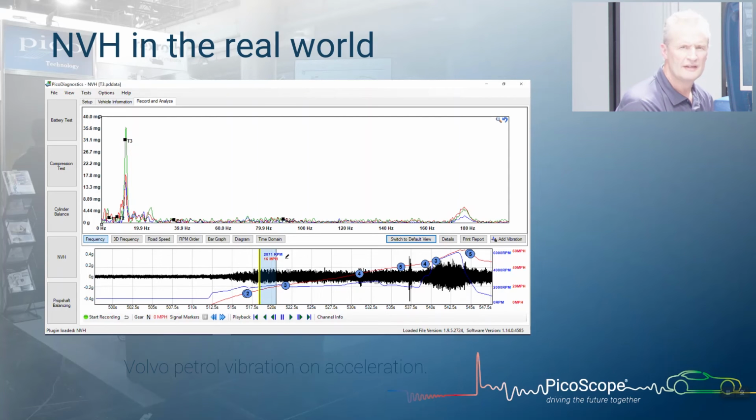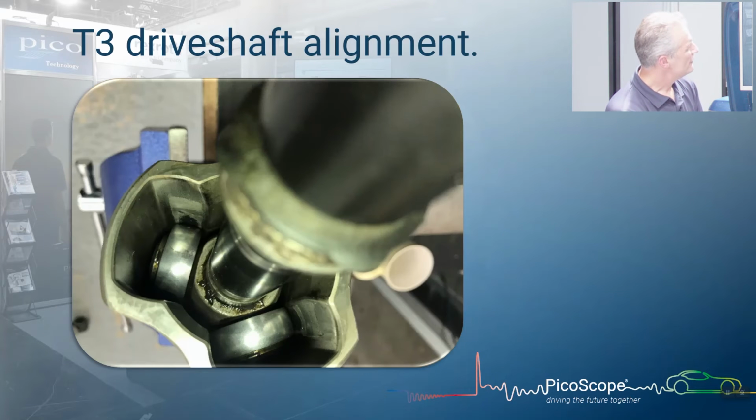So what typically can give us this scenario? Well, in the next slide we'll reveal this is a tripod joint of a drive shaft, and hopefully you can see that here we have a bright spot about 3 points around the tripod joint. So under full load we're getting movement of the shaft and misalignment of the shaft such that it generates 3 disturbances per revolution.